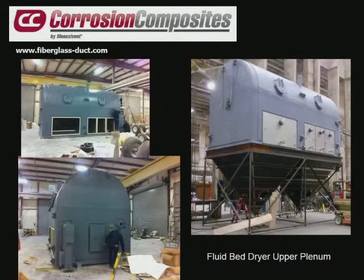What they're doing is they're drying CPVC powder, and the powder is blown through this as it dries. And the problem with CPVC powder is you can get hydrochloric acid condensate in there. So there's a real corrosion problem. It operates at about 180 degrees, and the condensate is very, very corrosive.